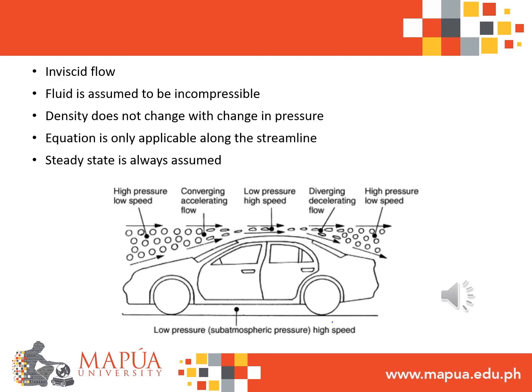The Bernoulli equation was derived from Newton's momentum equation under these assumptions. Inviscid flow, fluid is assumed to be incompressible, density does not change with change in pressure, equation is only applicable along the streamline, steady state is always assumed.